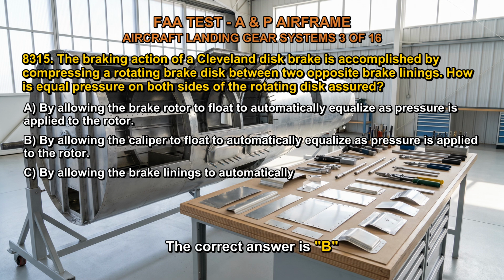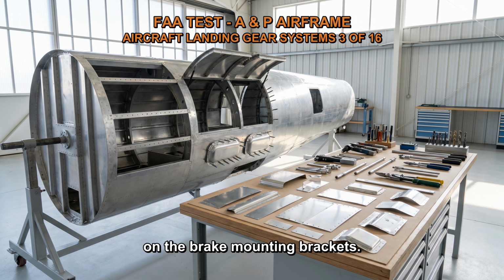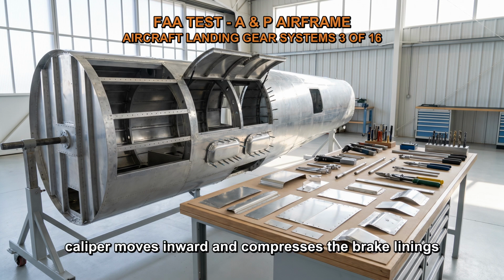The correct answer is B. The design of a Cleveland disc brake system incorporates a caliper that is free to move on the brake mounting brackets. As pressure is applied to the brake, the caliper moves inward and compresses the brake linings against the rotating brake disc.